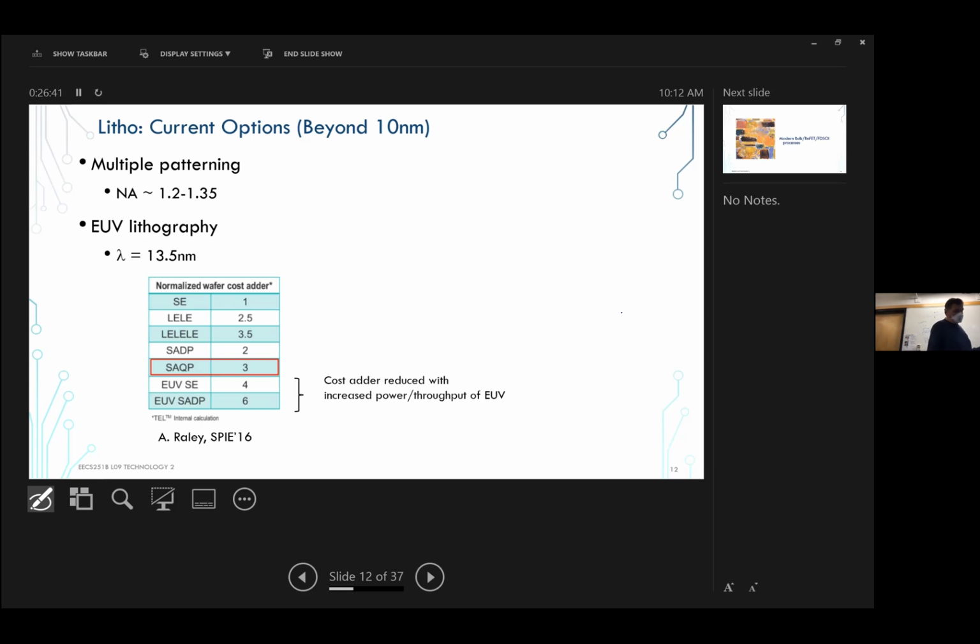But what was documented in Intel's case were the yield losses. Intel at their 10 nanometer node had to go to quadruple patterning in some layers, and they could not get the yields to look right. They got a lot of wafers out, a lot of things were done, but the yields were not looking right. That looked like not a good way to go.